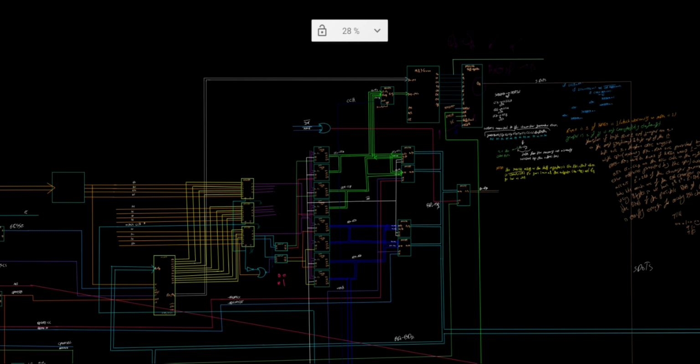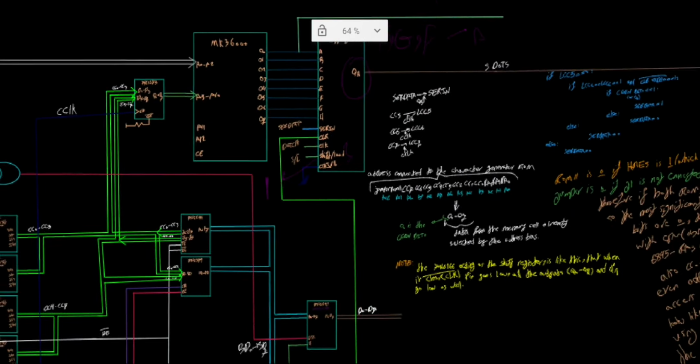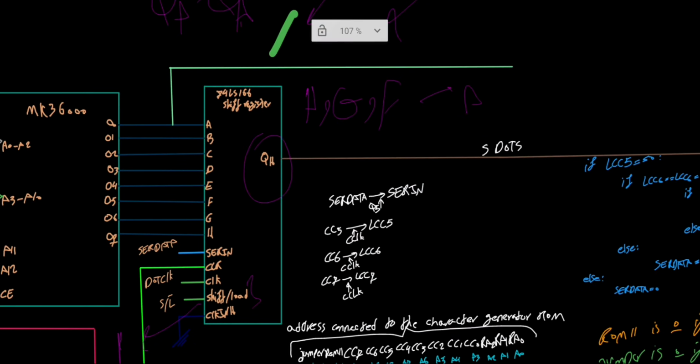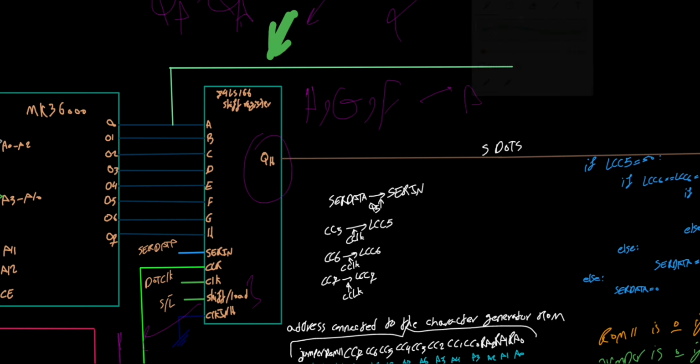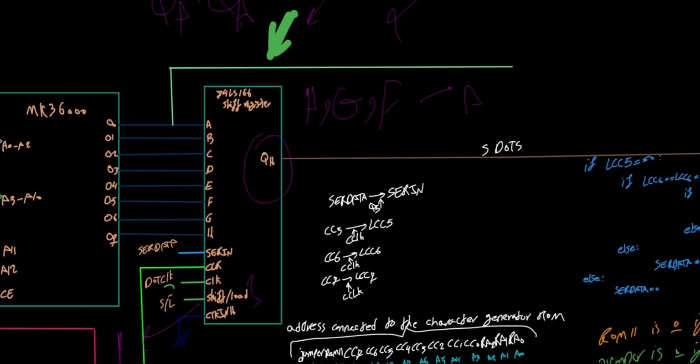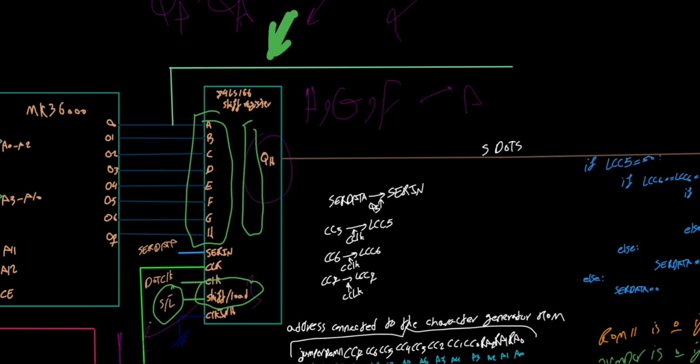This is the graphic card, to when the monitor would scan pixel by pixel. And if we look, this is the LS166 shift register. And as I said, the way it works is that 1 clock out of 9 clocks, SL would go low, the shift load. Therefore, whatever is on the input would go on the outputs, all the QA to QH, which obviously you don't have access to.